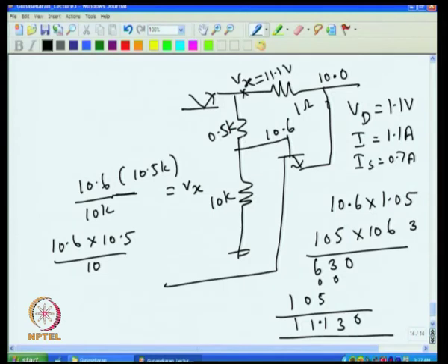If I keep this resistance larger, then I can make this ratio much larger. For example, I can make it 1:half by selecting this resistance suitably, that you can work out and see how to select for different amounts of current. So, essentially by selecting these two resistances, one can get different current for short circuit and different current for normal working. This is very important. If you do that, then one can limit the current at whatever rate is required for short circuit and whatever normal current is required for normal working. So, this is about foldback current limiting.